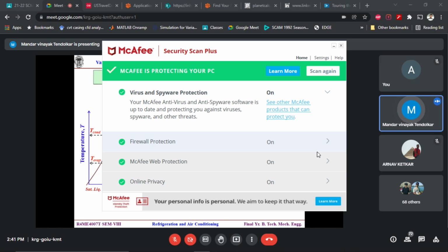And then this A2, the loss in the cooling effect. If you would have executed an isentropic expansion, this would have reached at point 4 dash, and the heat absorbed would be H1 minus H4 dash. But because of the isenthalpic expansion, it finally ended up at this point, and as such, the refrigeration effect is reduced for this 4 to 4 dash. Rest, 1 to 4 is common. Are you getting it?